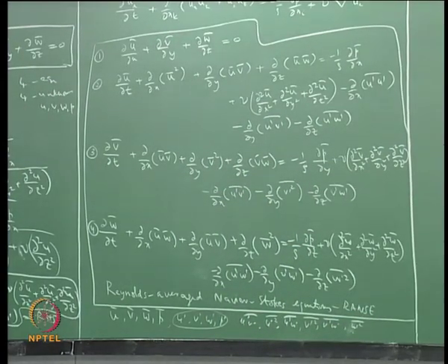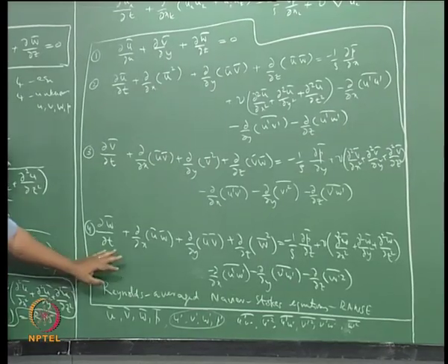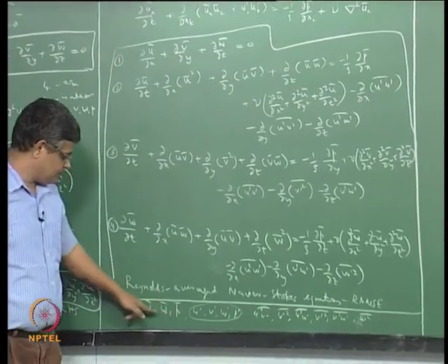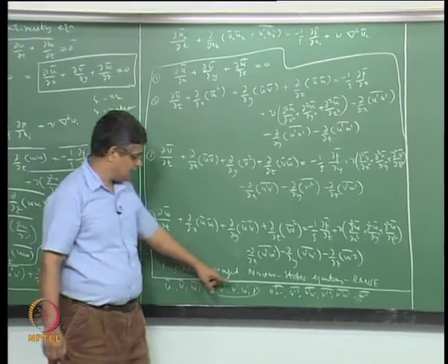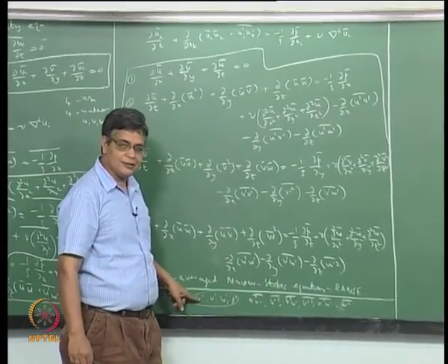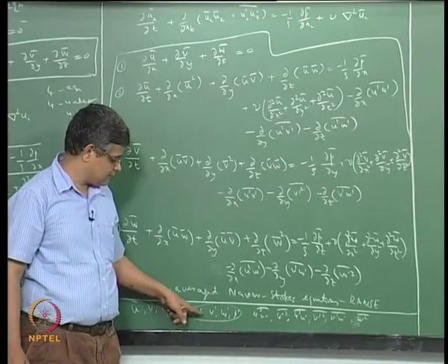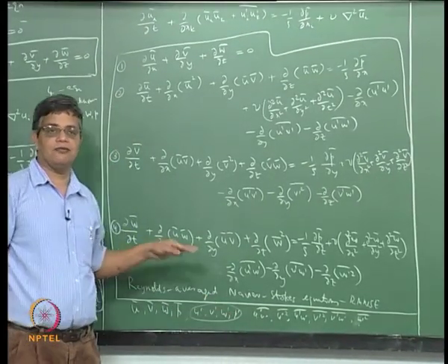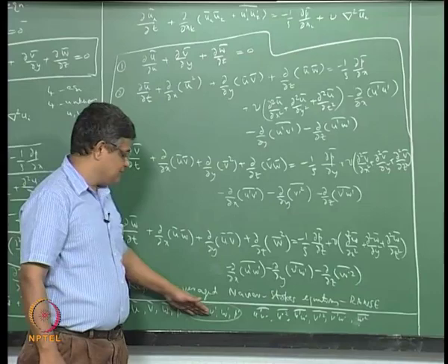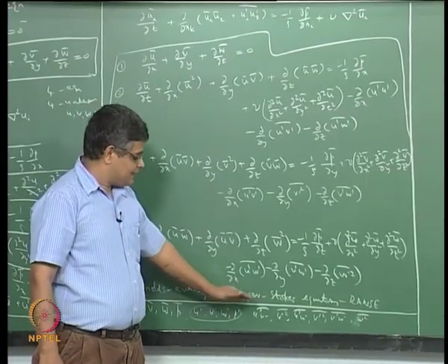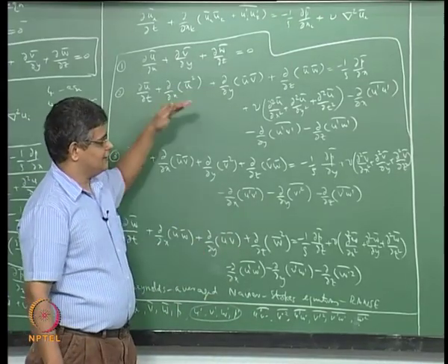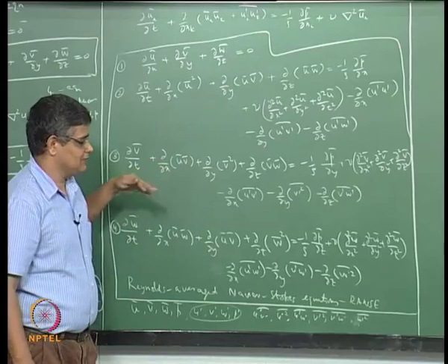So our time averaged Reynolds averaged Navier-Stokes equations contain 4 variables which are of interest to us and 6 additional variables in terms of the rapidly fluctuating quantities u prime, v prime, w prime, p prime, which are not of interest to us. Okay, so we would say that we are not interested in this, but it is necessary that we know these things, because only then is the time average form of the Navier-Stokes equations complete.